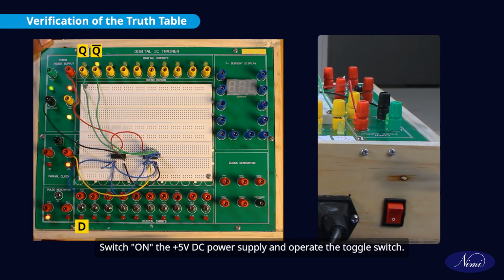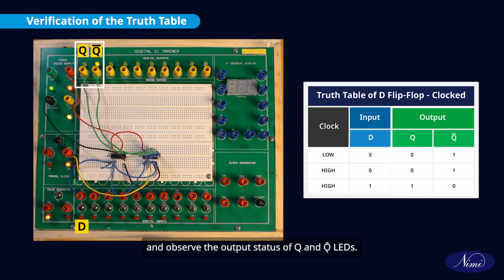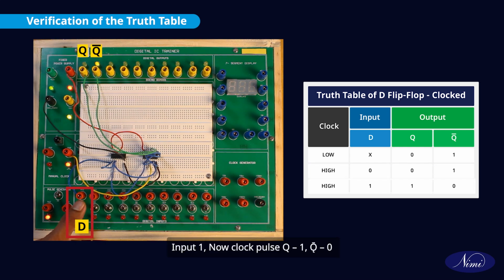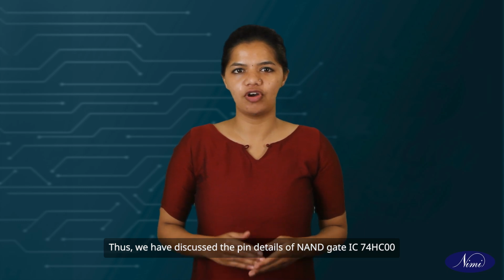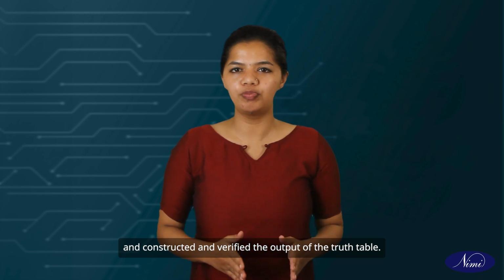Switch on the plus 5 volt DC power supply and operate the toggle switch. Apply different inputs to D flip-flop as given in the truth table and observe the output status of Q and Q bar LEDs. Input 0, now clock pulse, Q 0, Q bar 1. Input 1, now clock pulse, Q 1, Q bar 0. Thus, we have constructed D flip-flop using NAND gate ICs and verified its functioning with truth table. Thus, we have discussed the pin details of NAND gate IC74HC00 and constructed and verified the output of the truth table.